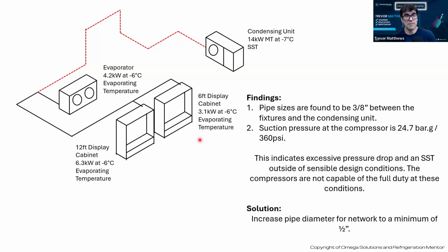And this is where I've seen many issues where that's exactly how you figure it out. You take it from the last evaporator, for example, and then you go do it at the inlet of the compressor, where I've had people tell me they had like a 12 psi or almost 1 bar pressure drop. They're running into oil issues, and that's how big of a pressure drop they have in their suction line going back to the condensing unit. So that's a quick check.